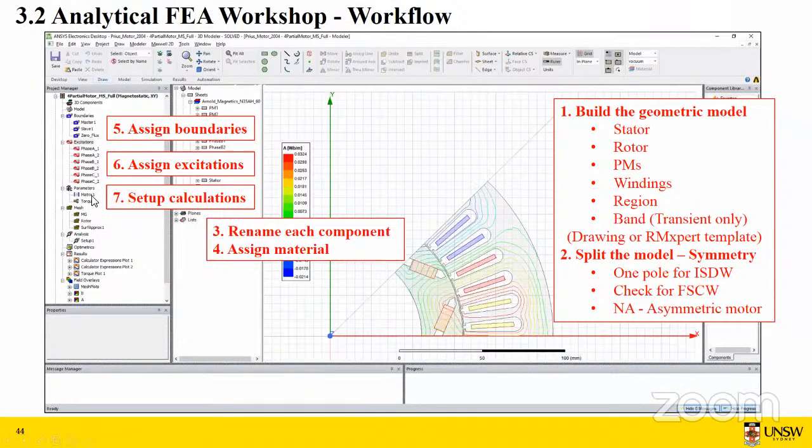So you need a matrix to solve the inductances, because we all know LA, LB, LC, and the mutual inductances exist as a matrix, mathematically. And for the torque, you need to let the model know whose torque you want to calculate. That's the time you need to set this. In this case, we want to calculate the torque acting on the rotor, so you need to select the rotor and the magnet, and then assign torque calculation to the rotor.